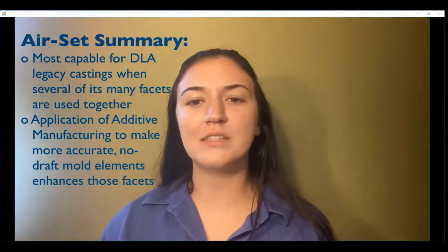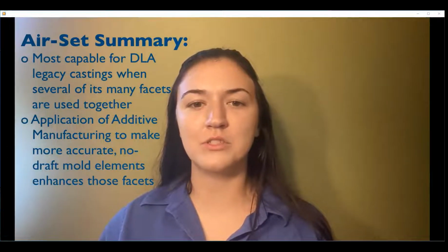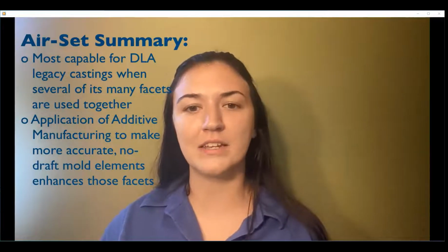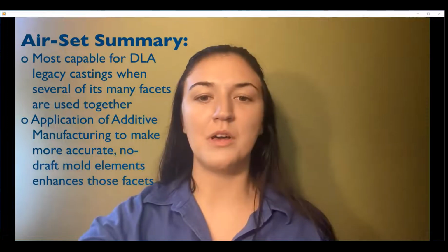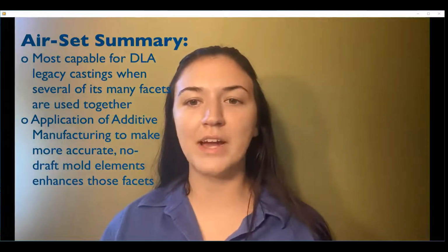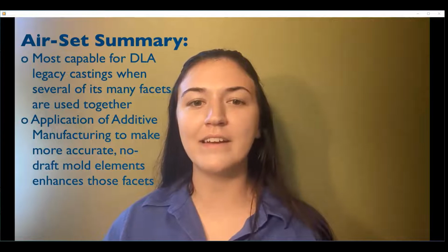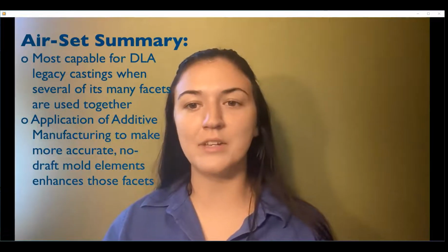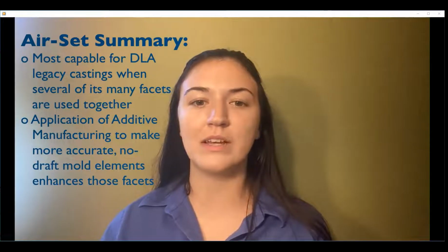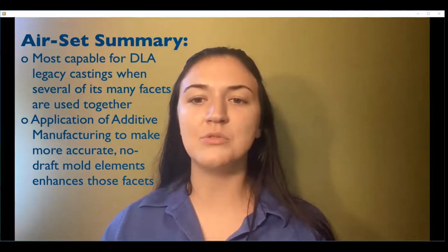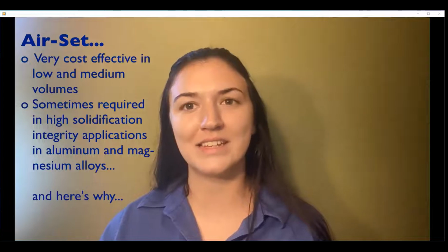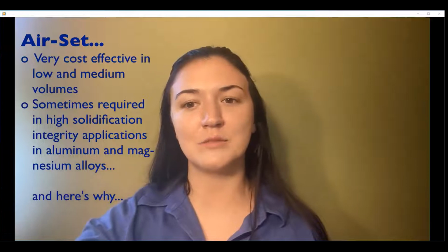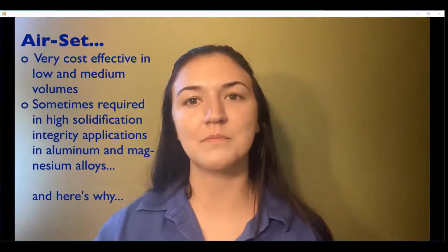Only when as-cast dimensional tolerances are difficult to achieve does the ceramic shell investment casting process have a significant advantage. Even so, the ability to use additive manufacturing technologies to print entire airset molds or airset mold elements with no draft and more accurate one-piece mold elements makes the need to choose the investment casting process less necessary. And airset sand castings are significantly less expensive than investment castings.